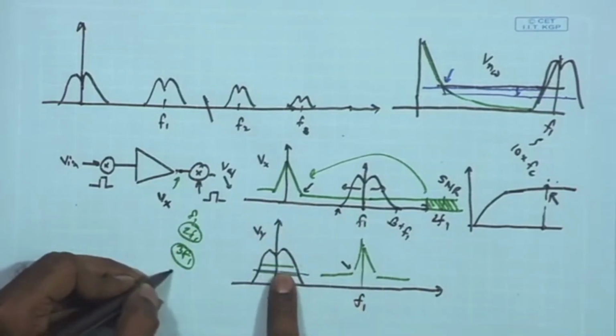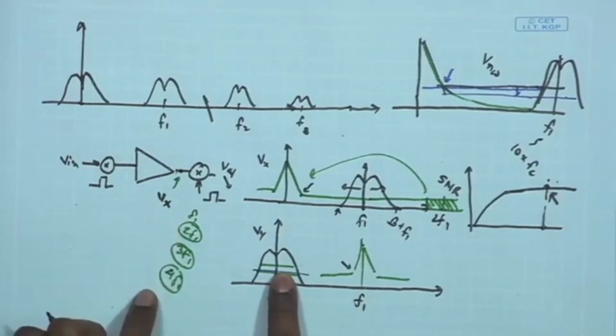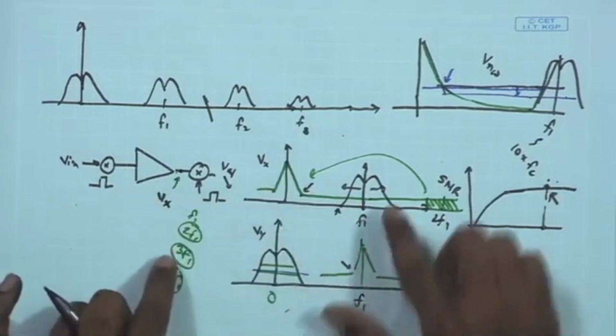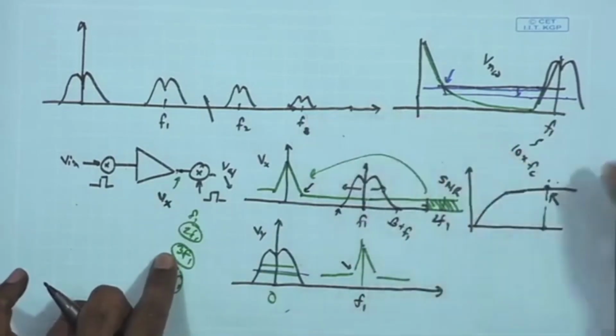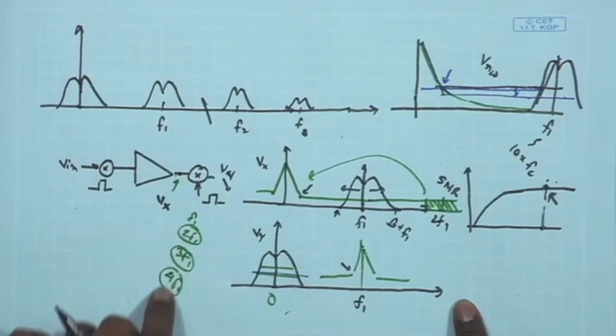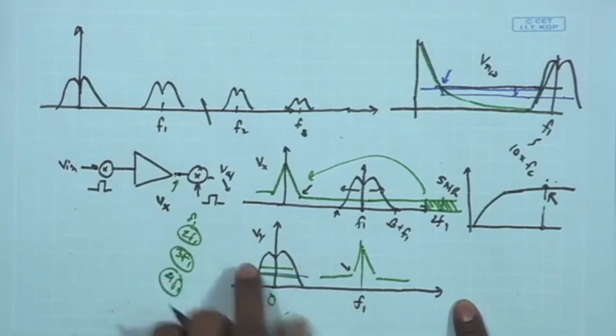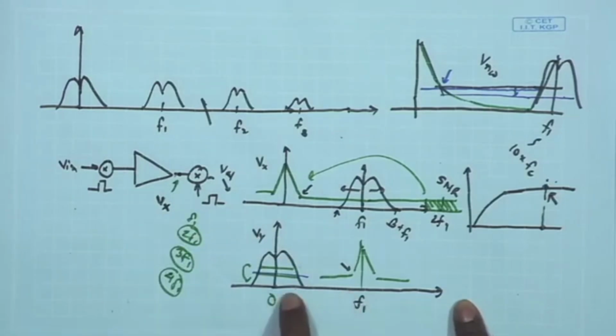So, of course, as we go towards higher and higher harmonics, their amplitude also diminishes. So, it is a convergent series, it is not going to diverge, and apart from that you also have some low pass filtering effect in the circuit, which is going to diminish the components at higher frequencies. But still this series converges towards a finite value over here, and we need to minimize that finite value, so that we can maintain a good signal to noise ratio. So, that sizing constraint also needs to be taken care of.